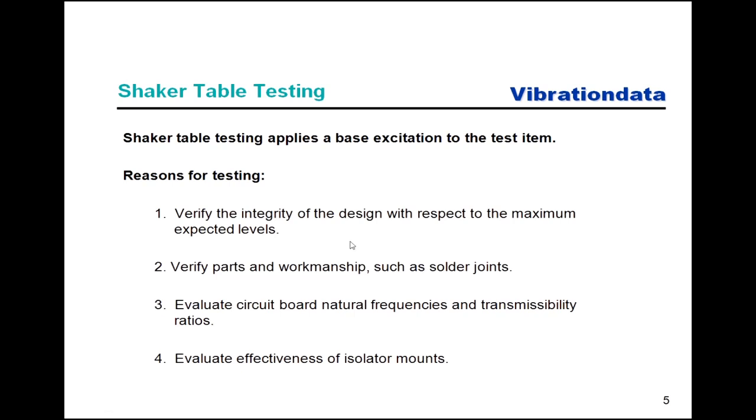So we do a proto-flight level somewhere in between, and we do a lot of cringing when we do that, because the act of testing itself is causing some accumulated fatigue cycles, but yet we want to make sure there's no latent defects either. So that's always agonizing. There's variations on this theme.